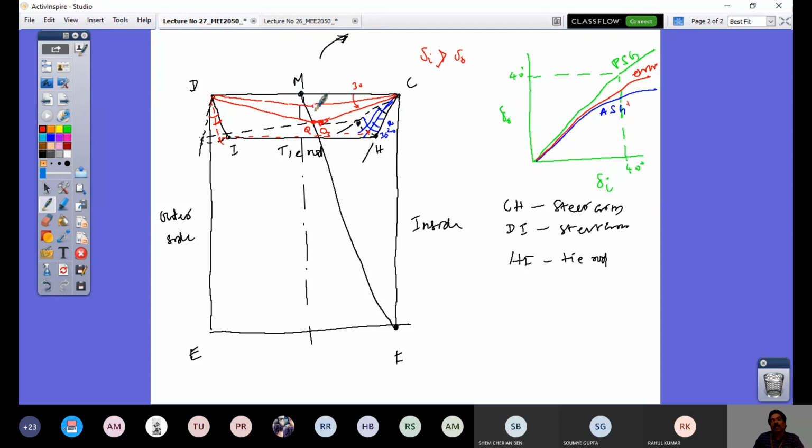So this is a point O1. Similarly, I get point O2. So this is all with the error. It is not lying in this. So this error is inevitable, which will be there in real time. And with that error, for the given steering angle of the inner wheel during the turn, you will have a corresponding outer wheel turn with some error involved.